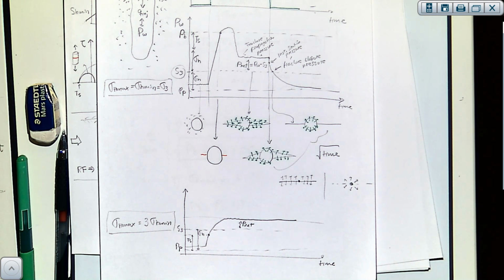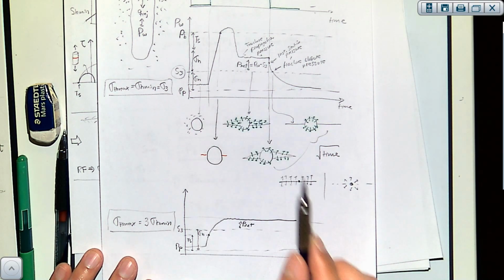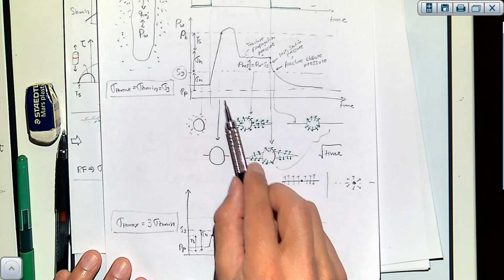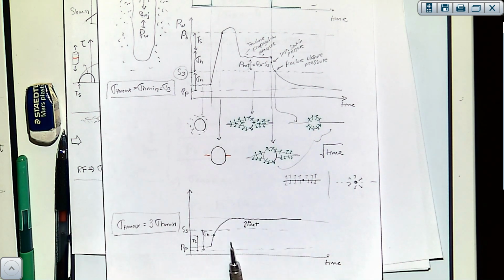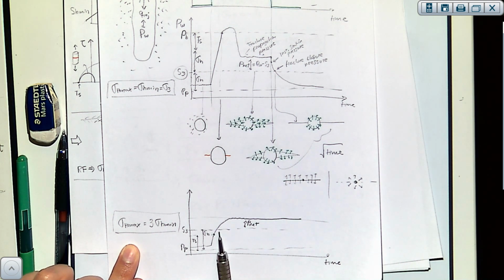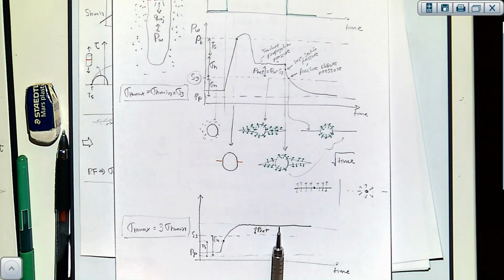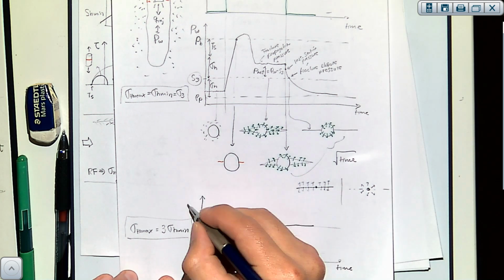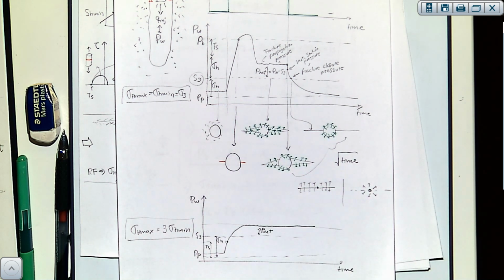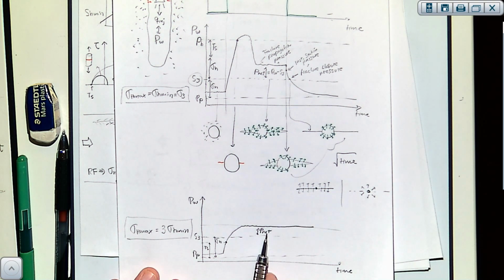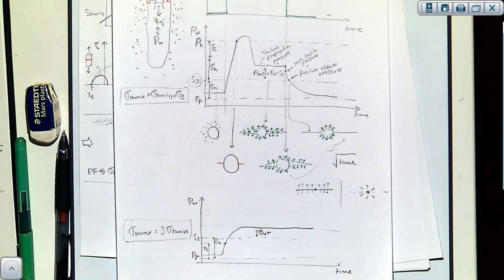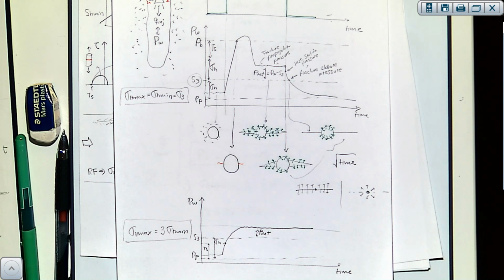The presence of the wellbore makes the stresses vary around the wellbore, and if you have an isotropic state of stress, that's the case in which stresses are going to amplify the most, and you have to increase the pressure the most. Some stress anisotropy is going to be a lot easier. Again, in order to have a fracture propagating in time, you have a net pressure which is positive.